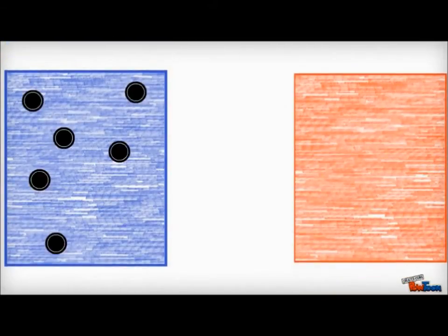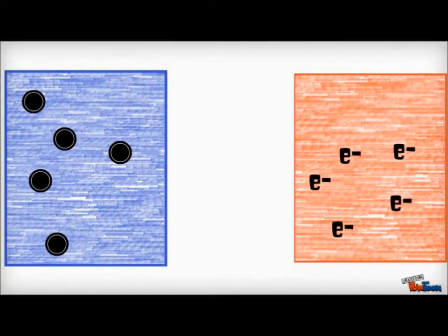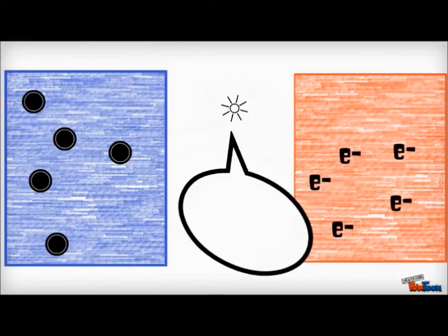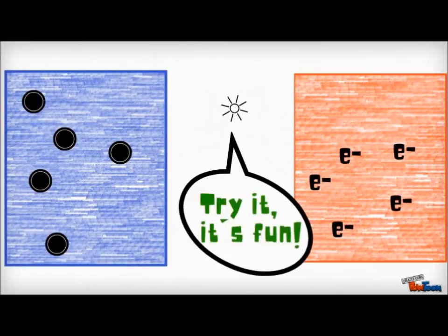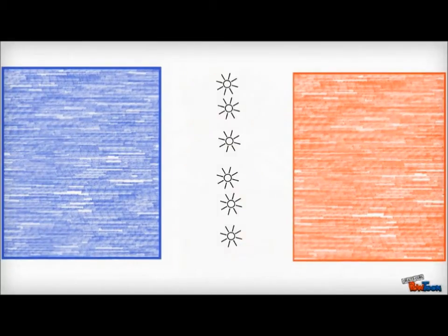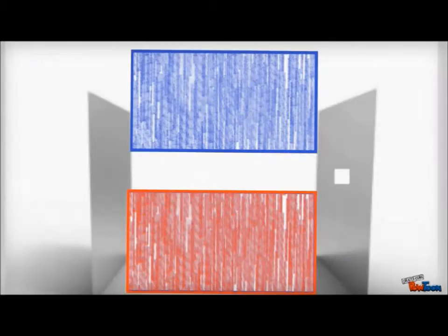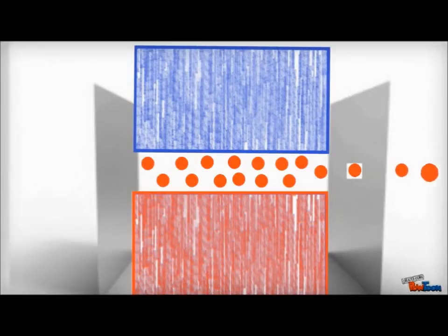When we supply energy to the p-n junction diode, the electron and the hole combine to release a photon. This stimulates the other electrons and holes to combine and release photons as well. The p-n junction is surrounded by mirrored surfaces to trap the photon of light. The photon bounces around the p-n junction. Now, due to stimulated emission, the p-n junction is filled with laser light, and a vast majority comes out through the hole in a straight line.